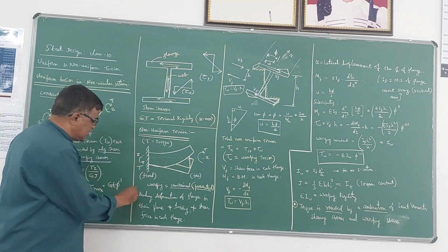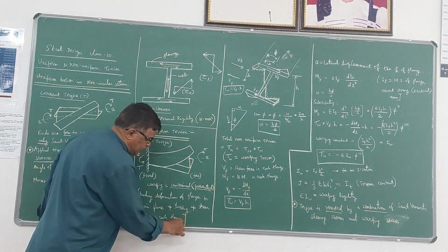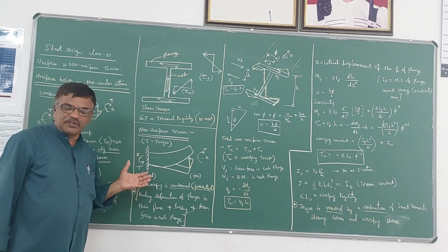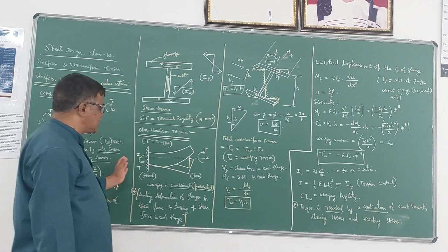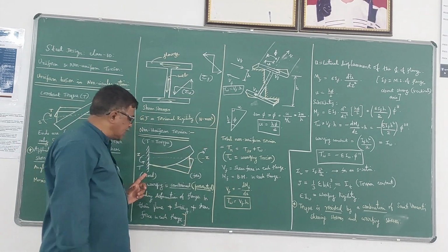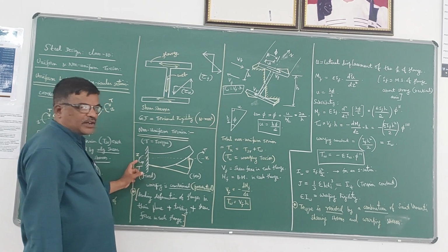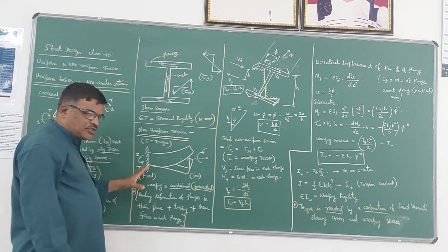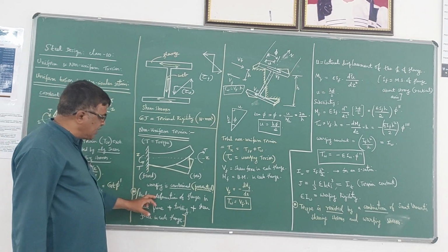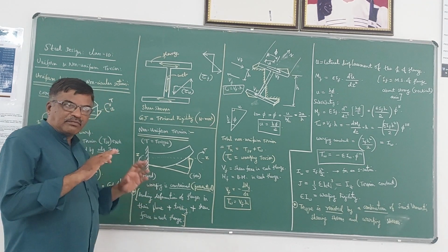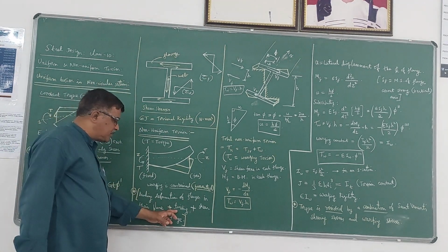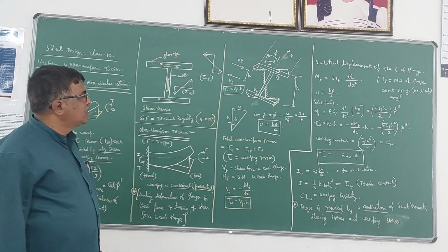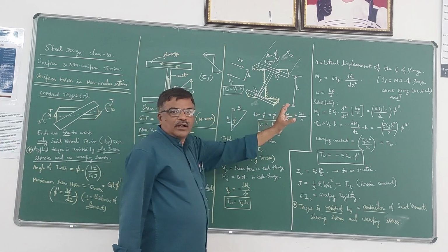So in such a case, please observe that there will be three things. You have to remember. In non-uniform torsion, when one end is fixed and another end is free, and it is subjected to a torque like this at the end, definitely another reaction torque will develop here in the opposite direction. In this case there will be three effects. One is the bending deformation of the flanges in their plane. So bending effect will be there for the flanges, and twisting effect also. In addition to that, shear force in each flange will develop. So this is the example for non-uniform torsion.